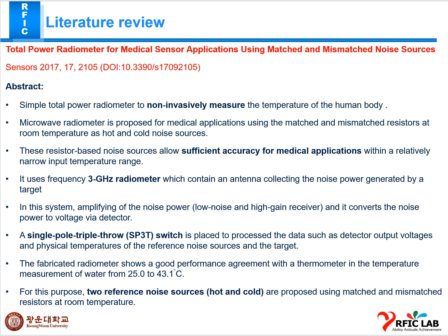It uses the detector output voltage and physical temperature, and a noise source has also been used. The fabricated radiometer shows good agreement with the radiometer temperature, and measurement of water ranges from 25 degrees Celsius to 43.1 degrees Celsius, using two reference noise sources, hot and cold, made from matched and mismatched resistors at room temperature.